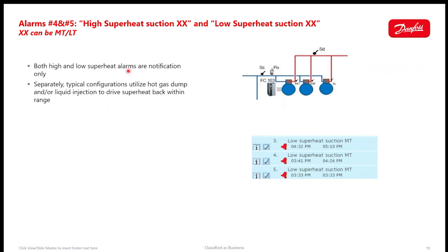This is notification only. From a troubleshooting standpoint, what we want to consider is for low superheat, it could be something from the case level. So floodback's always a possibility from the case side. That's HFC, CO2, any system type. That's something you always want to take into consideration.